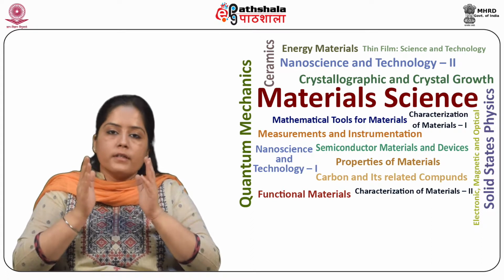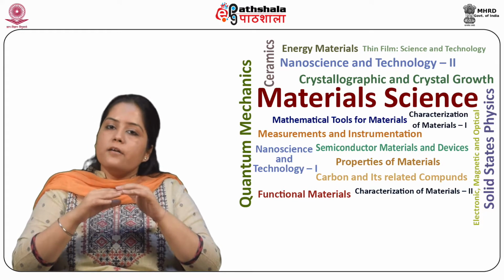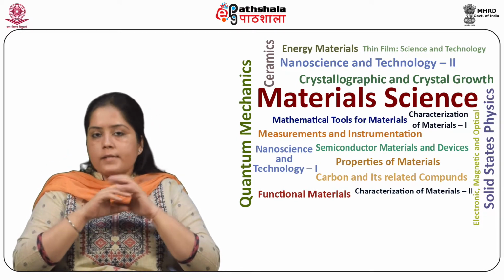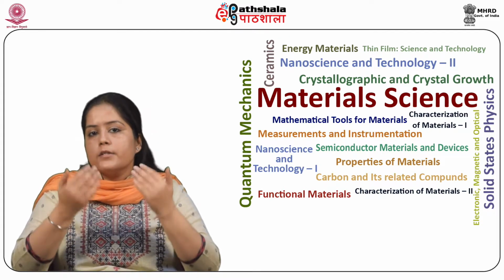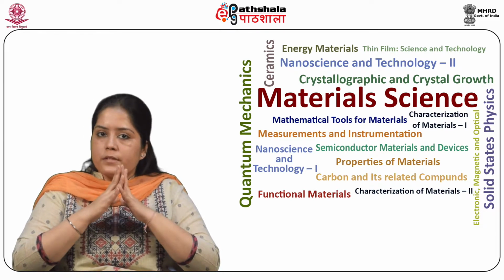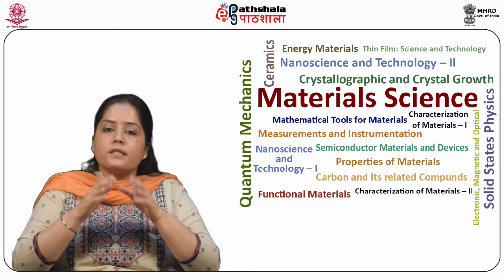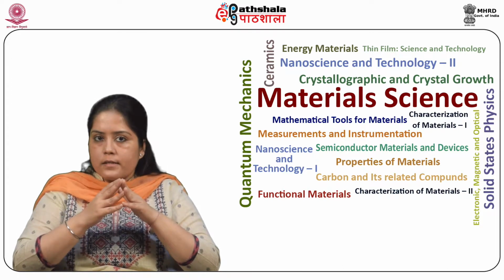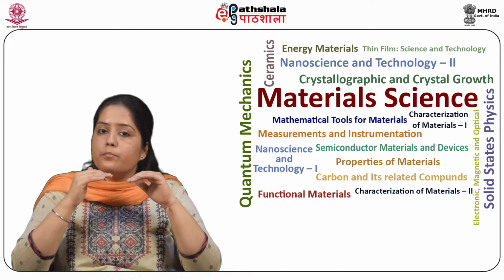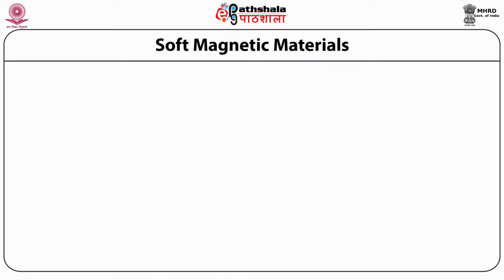The advantage of these alloys is that they reduce the power losses in transformer cores by a factor of 3 or more. This happens by the addition of silicon to iron, which increases the electrical resistivity to a few tenths of micro ohm centimeters, leading to lower power losses. Also, the subsequent development of strongly textured steels led to even better quality of steel, with further reduced core losses.